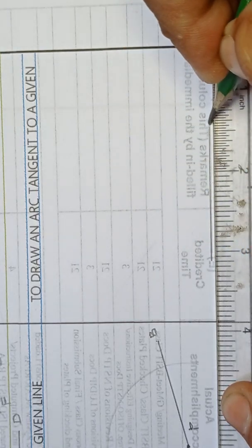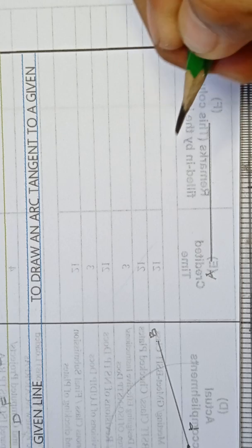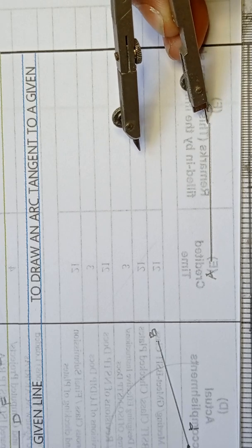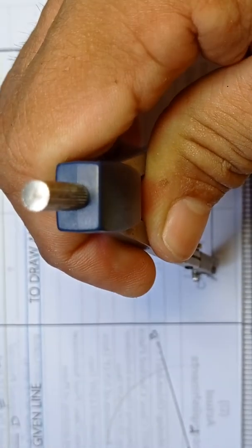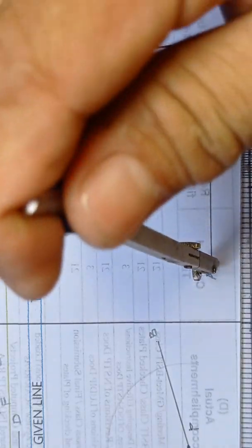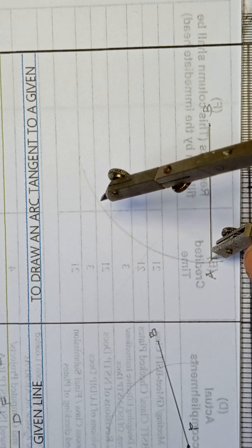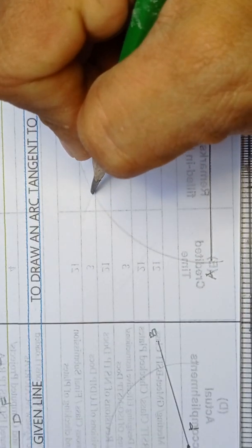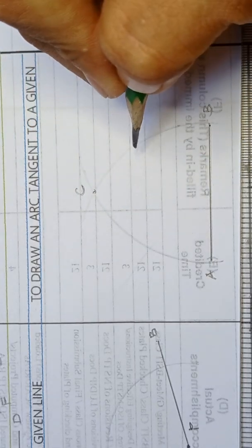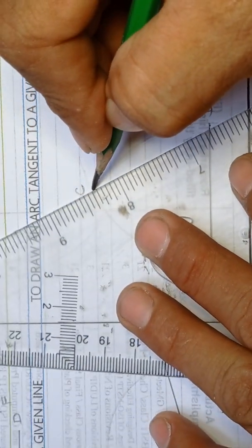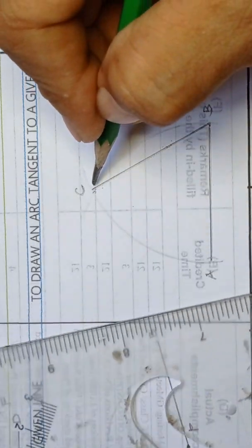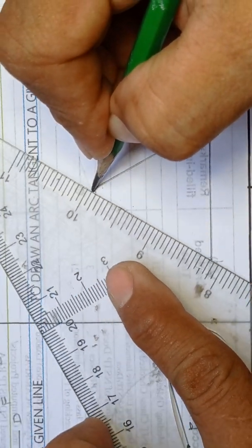So, we use this line AB, mark it A and B, and then draw a very light arc towards point A, going upward, and using point B as your center, then start from point B going upward. And the two intersecting arcs create a point, that is point C, and then connect point C and point A to determine the equilateral triangle.